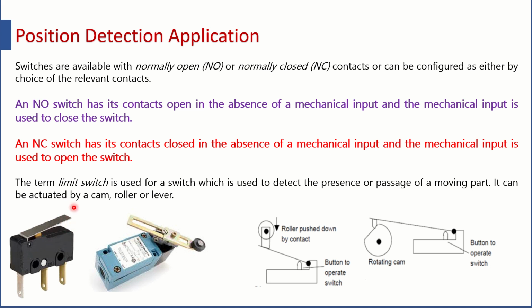Now you may ask, why should I press it? Because the machine wants to know whether the workpiece is there or not. This can be done very easily by drawing a line on the table and aligning your workpiece with it, in such a manner that whenever a workpiece is aligned with that line, it will automatically push the switch.